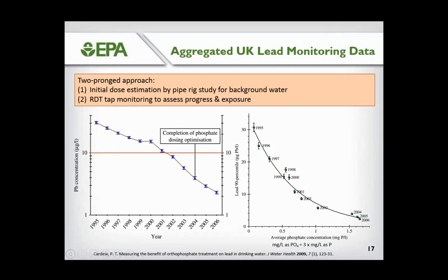And the nice thing about this kind of sampling program is that while you take lots and lots of samples, they're not as invasive, and they give you a more direct relationship to the exposure that people have under normal water use. It's also a very good direct comparison of the effectiveness of the treatment on both dissolved and particulate lead because it doesn't differentiate.